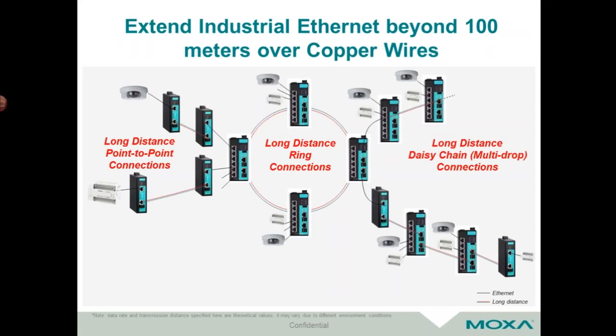The nice thing about DSL extenders as well is that they're extremely flexible in terms of what you can do to your topology and how far out from your main control center or main control room you can extend them. There are two main types of Ethernet extenders on the market. One is a standalone Ethernet extender, and one has Ethernet ports built into it. The standalone DSL extenders typically take in Ethernet on one side and put out DSL on the other side. So they're useful for a onesie-twosie run off of a main control area.